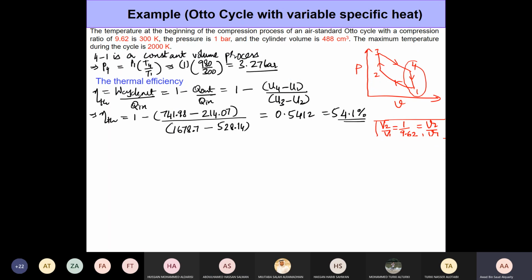But the correct answer is the fact that it's a closed system, because even if it was a process where you're having constant volume, but it was not a closed system, then you would have to take enthalpies because there could be some flow involved with it, right? So since it's a closed system, from the energy balance we'll be getting internal energies. You get enthalpies primarily when you're dealing with open systems.